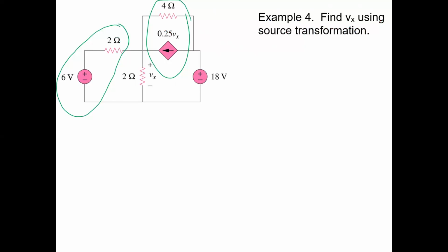And if we do that, let's look at this thing. In this case, the transform would require a current source that has an IS of 6 volts divided by, right, it's Vs over R. So it's going to be 6 volts divided by 2, which is going to be 3 amps. And up above here, you have Vs, which is going to equal an R IS here.